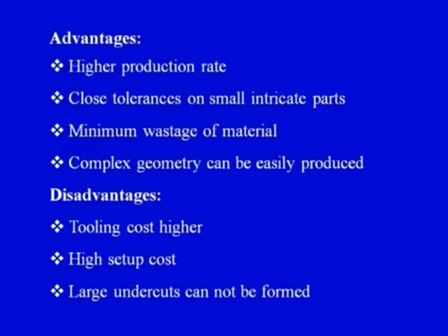There is minimum wastage of material because a metered amount of material is entering, and finally we are pushing the required material into the mold cavity. Yes, there would be some material left in the sprue which later has to be cut off, but still the amount of wastage of raw material is minimum in the injection molding machine.